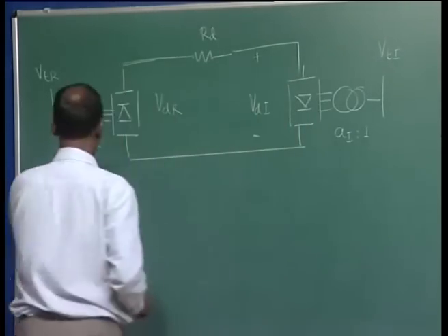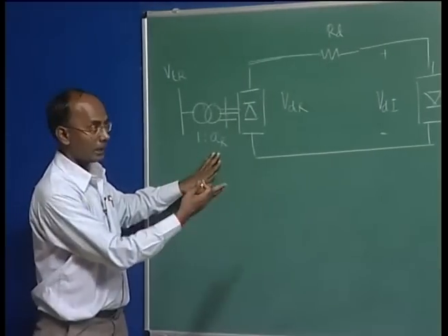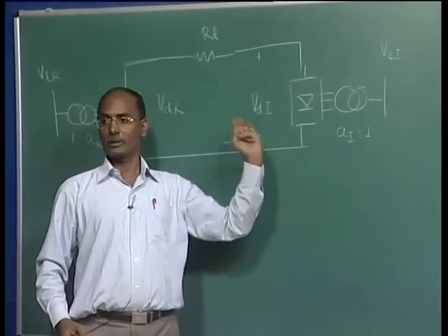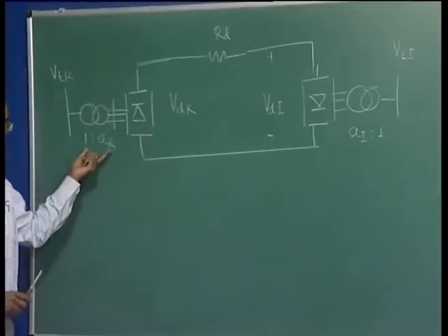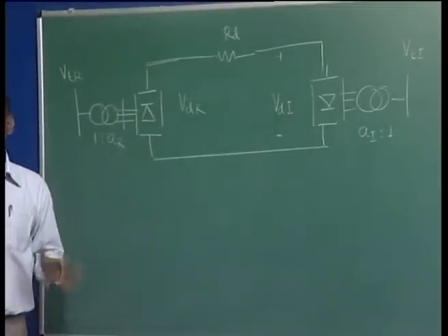So that is why you can see the tapping is represented on the DC side here, and here also I am representing it on this side. This is the reason we represent this OLTC in this way for solving our AC-DC load flow.